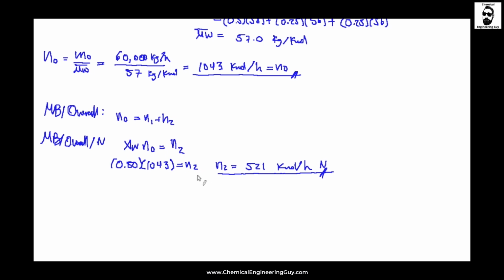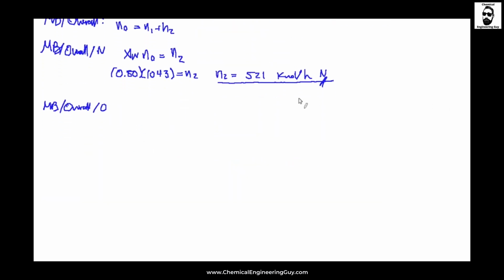Now what else can we do? Let's do a mass balance for octane. Now you know you have your system, you have no inlets, you have only outlets, and there's a production term here. So inlet minus outlet plus production minus consumption should be equal to the accumulation. At steady state, with no consumption, we're only producing, and there's no inlet.